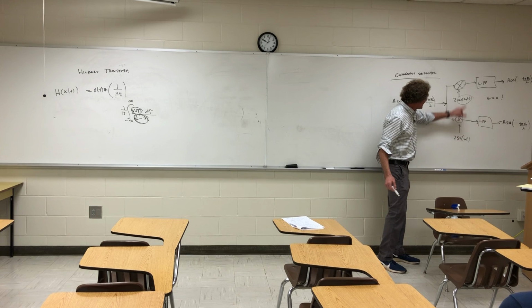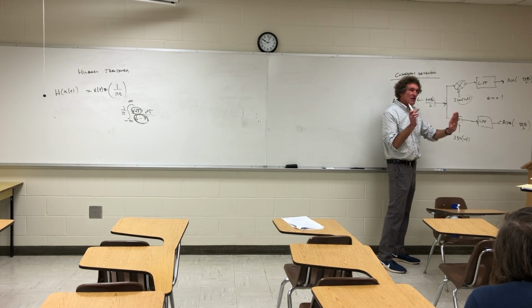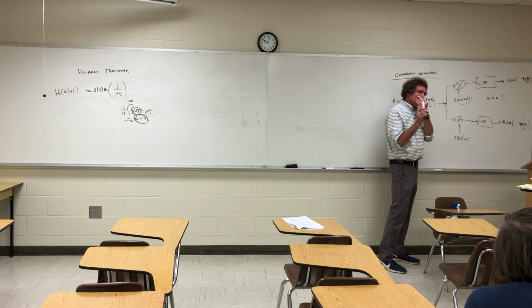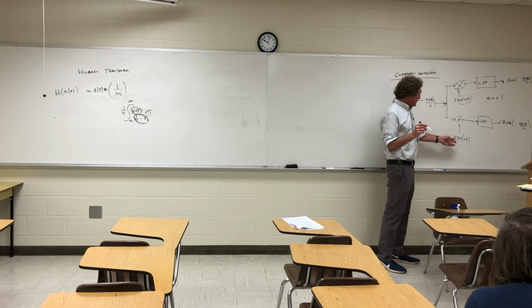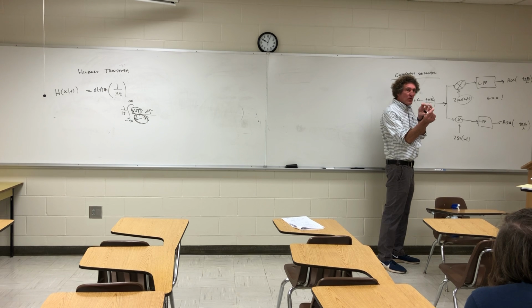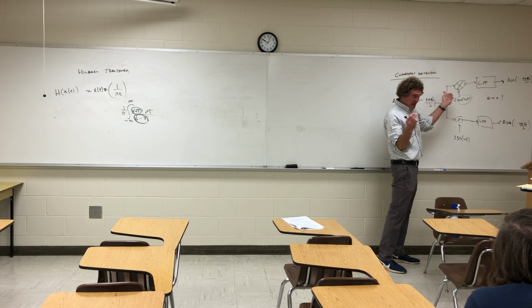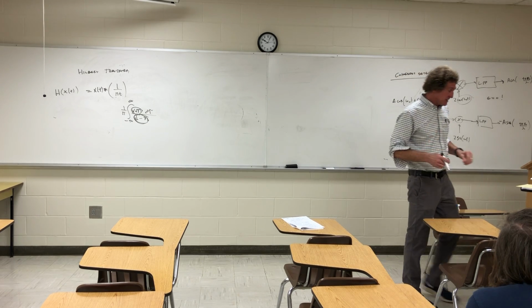I mean, to do this phasing is very, very hard. To get a cosine and a sine just off by a quarter, I mean, literally by 90 degrees, they do it with delay lines usually. You know what a delay line is? That's typically what they do. But the problem with all this is that local oscillators, as stable as they may be, wobble. And whenever you get wobbling, it's not a quarter wave. It's not pi over 2, sorry, 90 degrees phase. That'll change, and that little bit of phase change disrupts signal processing. So please keep in mind, it's so important to make sure you have exactly that pi over 2 phase change.